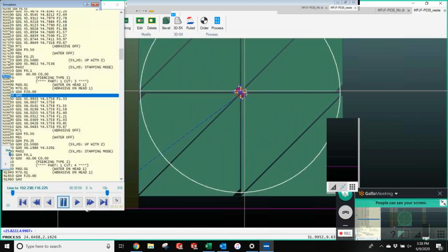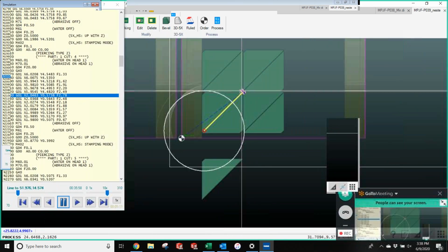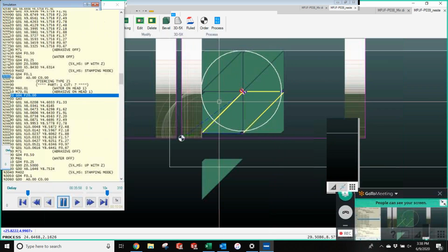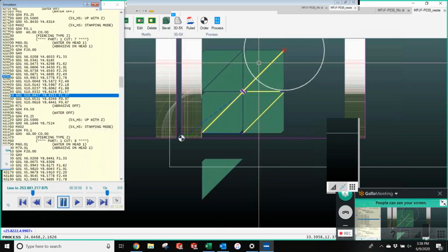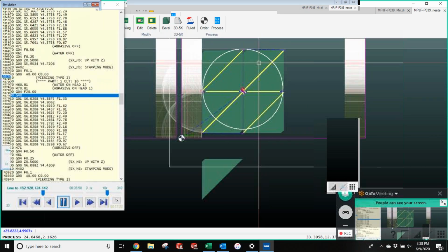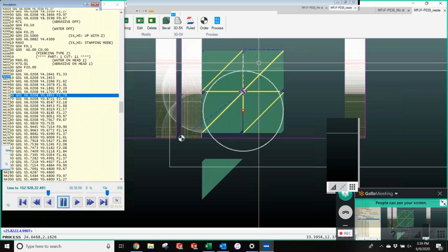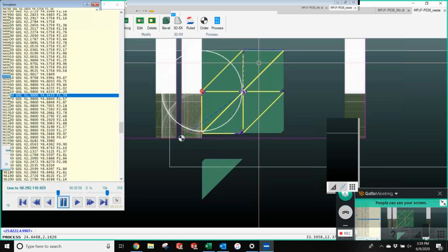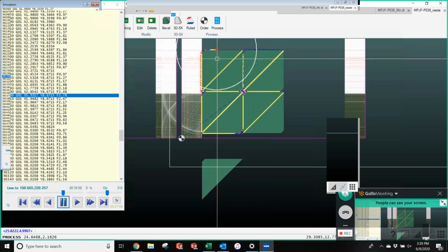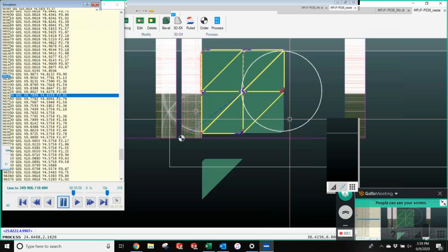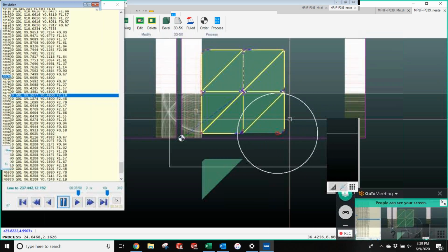So basically it's gonna cut a little area there in the middle and then it's gonna do a pierce and cut along there, pierce and cut there, pierce and cut there, and so on. And given the size of these parts, where they're small and they might fall into the tank, you probably wouldn't want to common line cut these. But again, for bigger parts that have long straight edges, you can save some time by doing something like this. Okay.